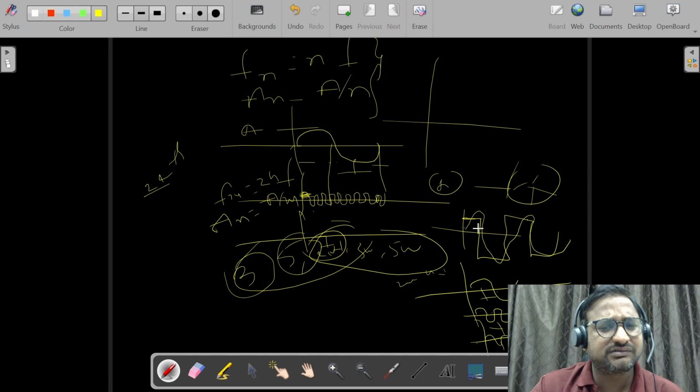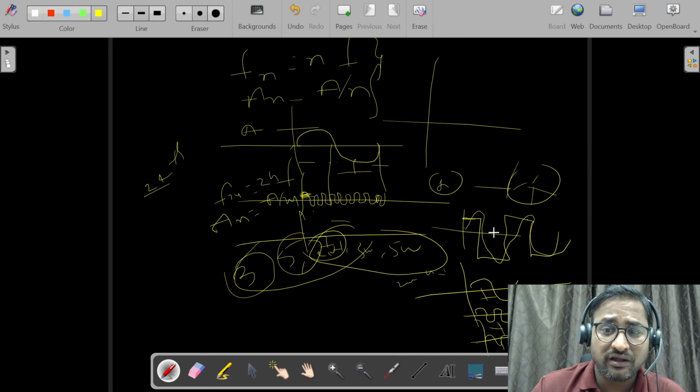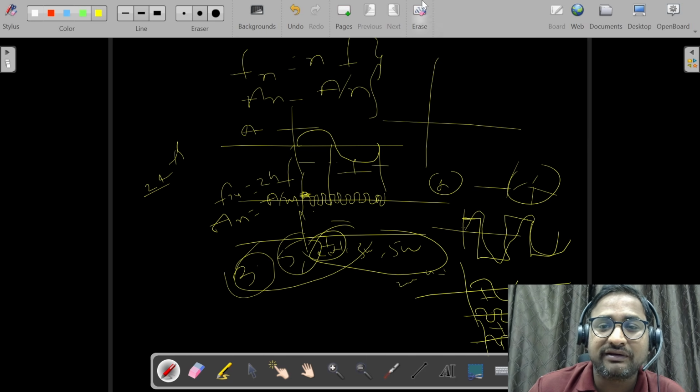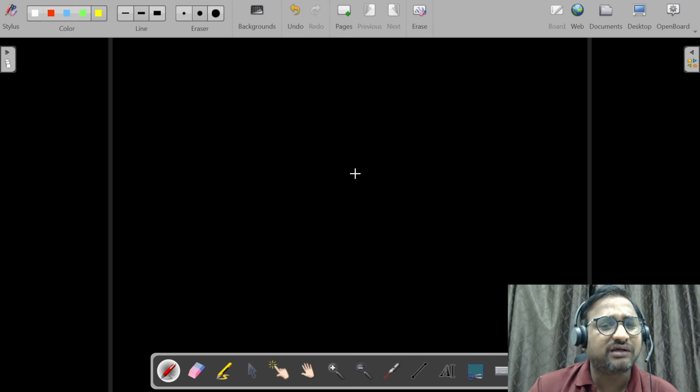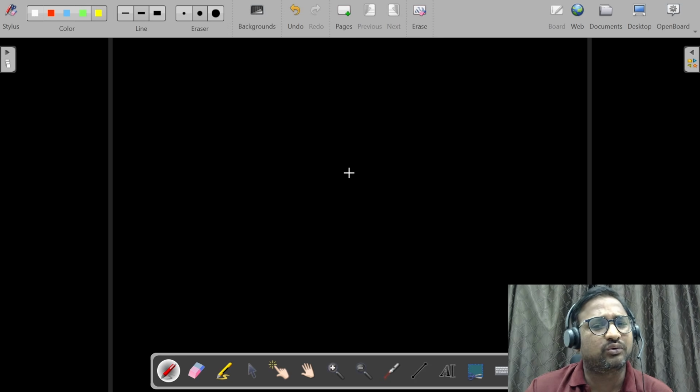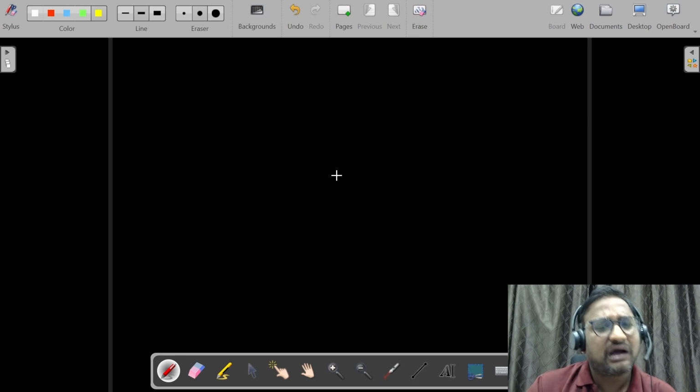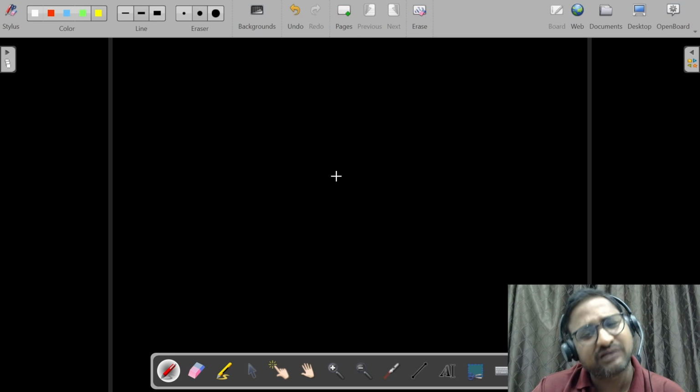See, I am giving this square wave pulse to the ceiling fan, so I need to decrease this 3 omega and 5 omega. In what way can I decrease it? In order to decrease that, we will come into power electronics. In power electronics, there are many methods to reduce the harmonics. Due to time constraint, I will explain